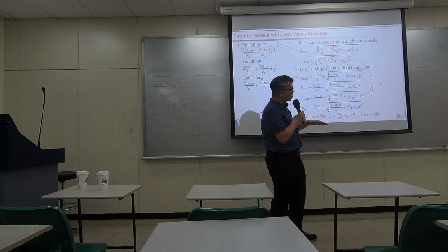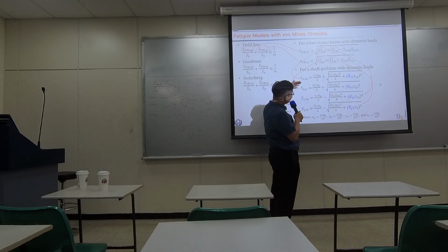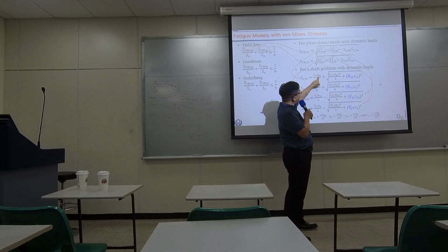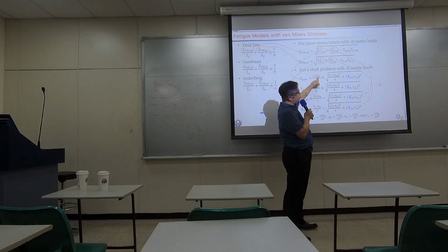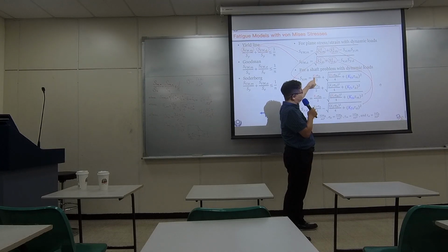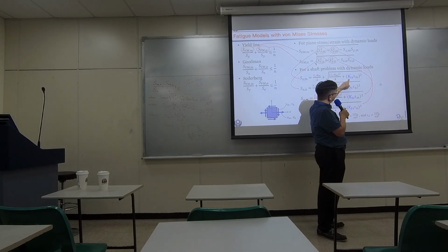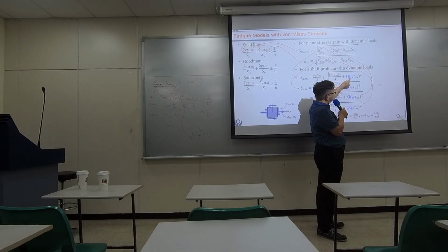The amplitude part changes with time. So for all the mean stresses, we treat them like the static ones. So for the stress concentration factor, we can use the static K. Same here, this is the mean of the shear, so we can use the static K.